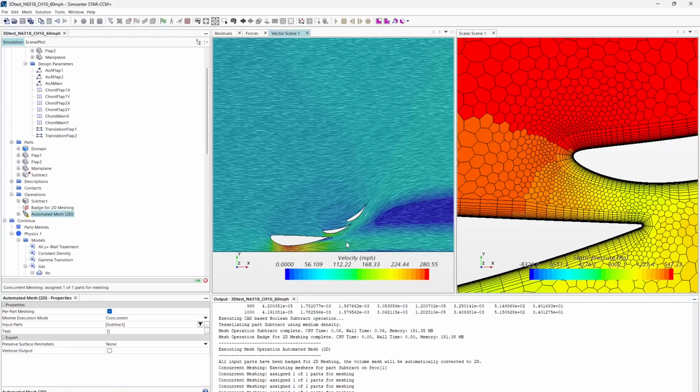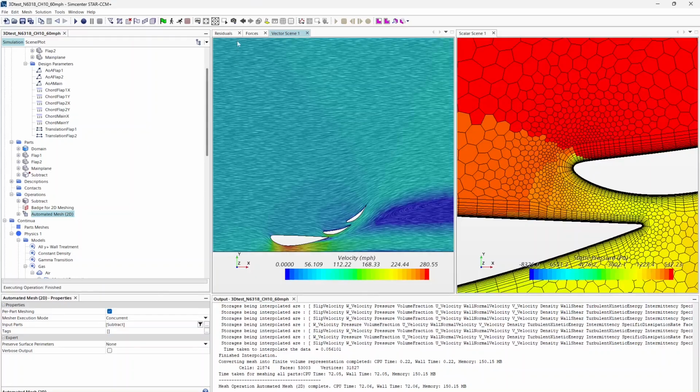And then take this 2D model, expand it out to a 3D model, and then run your best 2D model as a 3D model and make any changes that you need to from there. Additionally, this will simplify some of our center of pressure calculations, which we will do if we like the results of the simulation enough, which hopefully here in a second. Yep, okay, perfect. And so we've remeshed, and now we can go to solutions, clear solution.